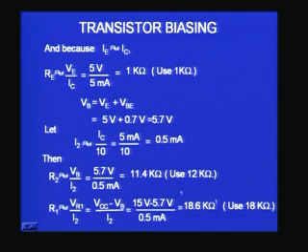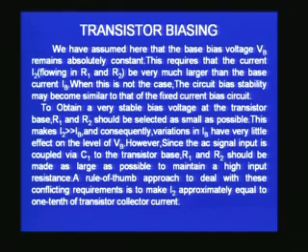So with this you can see that we have decided what will be the values of the various currents IB, IC, IE, and we have also found the different voltages and the different resistors R1, R2, RC and RE. Therefore we have completely designed the voltage divider bias with the emitter current biasing. Right. Now I already mentioned to you that IB should be very small compared to I2. This is a very important condition, when then only the transistor biasing will be stable. The stability of the biasing is a very important consideration.